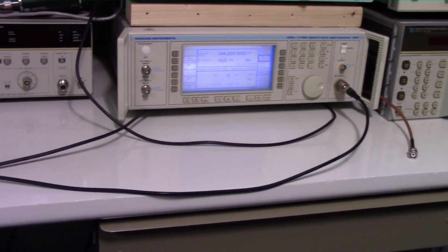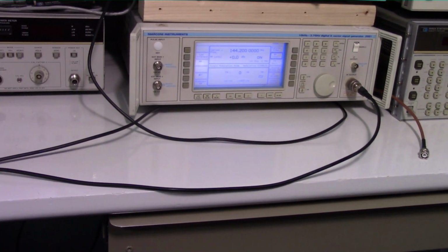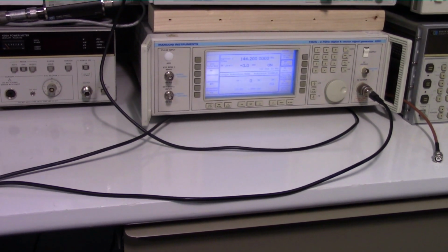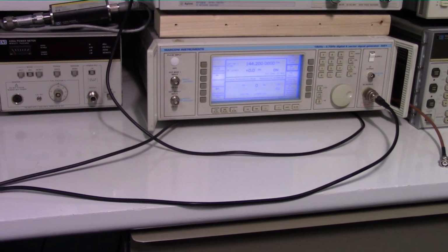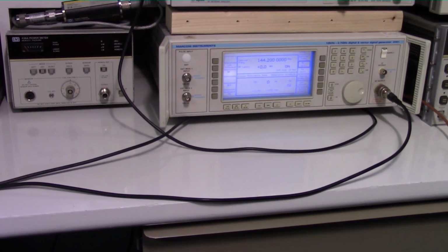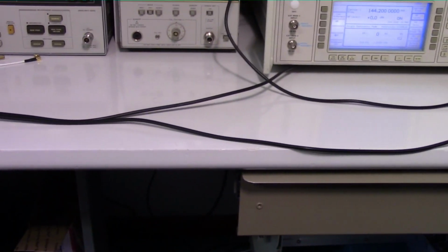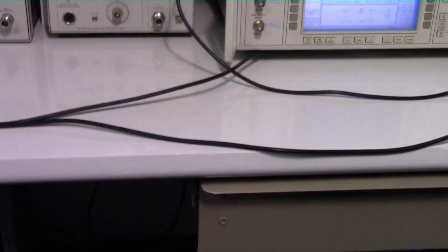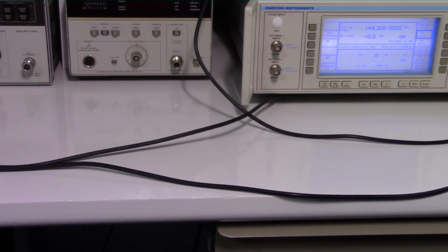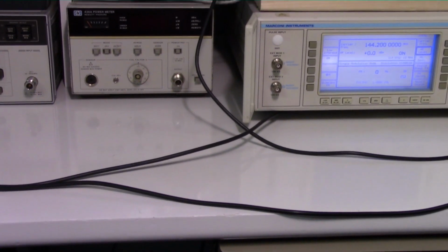So be very, very careful with cheap cables. Don't use them to make sensitive RF measurements, or when you're trying to make MDS measurements when you're expecting low levels. There's a lot of leakage occurring in these cables. Not only are they emitting RF, but they're also susceptible to RF.